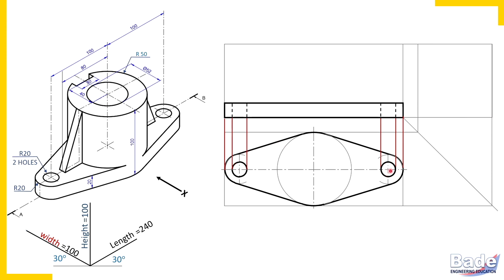But right now initially we are projecting these holes also. So holes, dotted lines in the front view. Now I projected the height of the plate in the side view, 20 millimeters. Check these two red horizontal projectors and draw end projectors from top view to side view. And this is how you have completed the rectangular block, that is the side view of the plate.